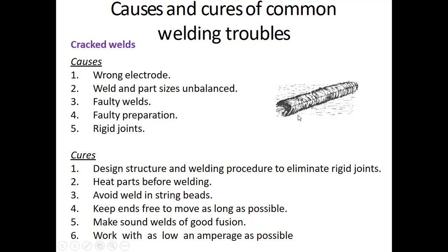Heat parts before welding. So to avoid those cracks, one thing you can do is preheat, right? Heat parts before welding; preheat is what we can call it. Avoid weld in string beads. Basically, you have this terminology in welding called beads, right? So that is to be avoided.